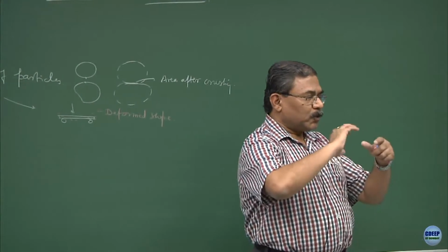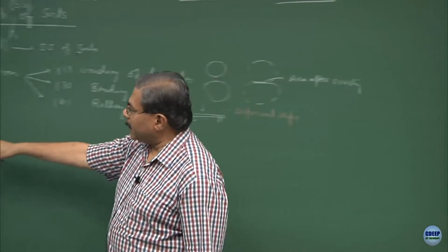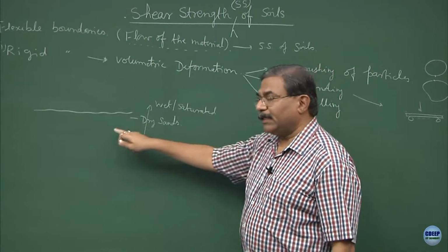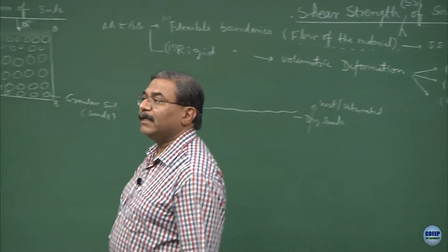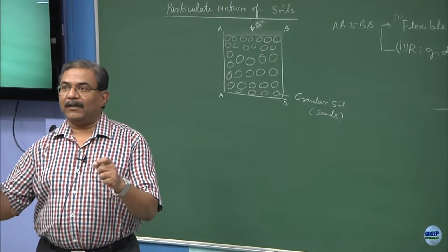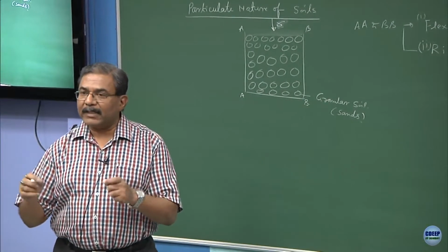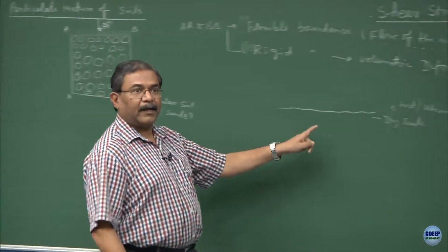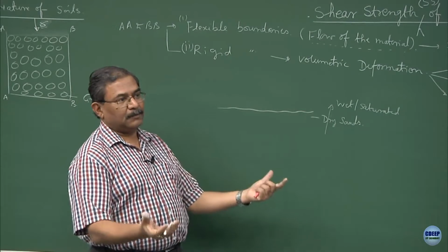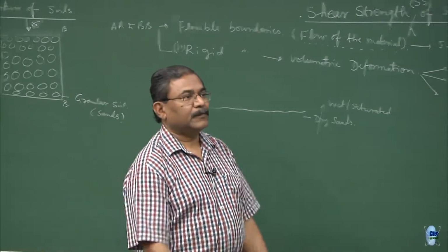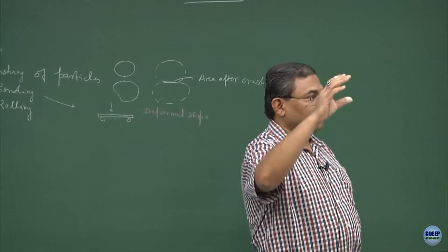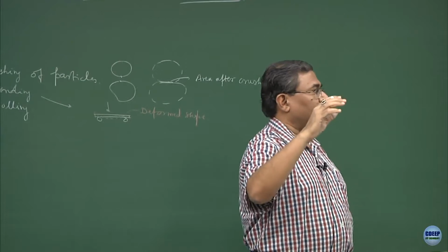There is a switch over of the mechanism from a dry system to the wet saturated sands. Water has entered into the pores and water provides tensile strength, clear. So, the first time I am using the word strength of the material, and from where is strength coming? Just because of the water entering into the pores. The moment this sand again dries up, it becomes loose, no effect. And then we have talked about the bulking of sands and all those things. The density is maximum at the point where you have bulking occurring, fine.